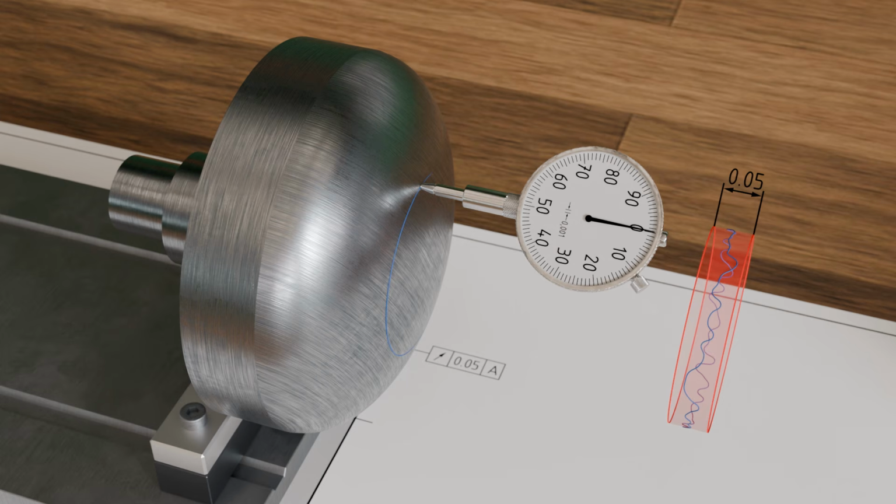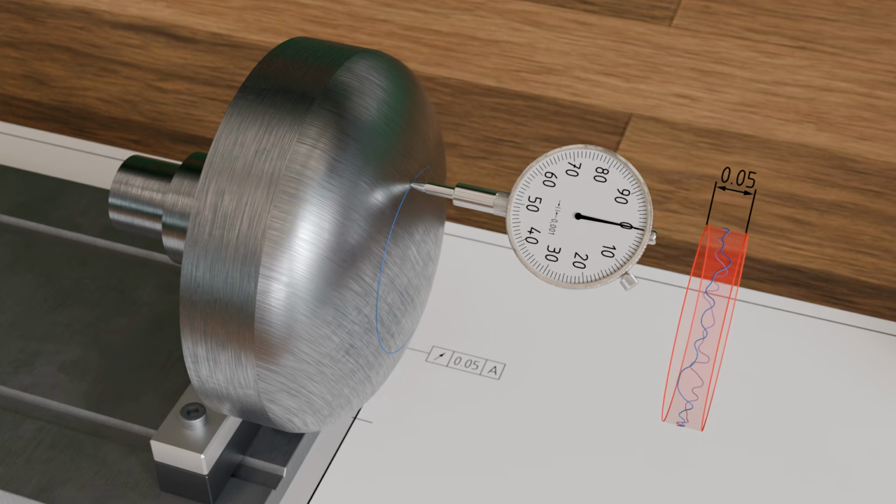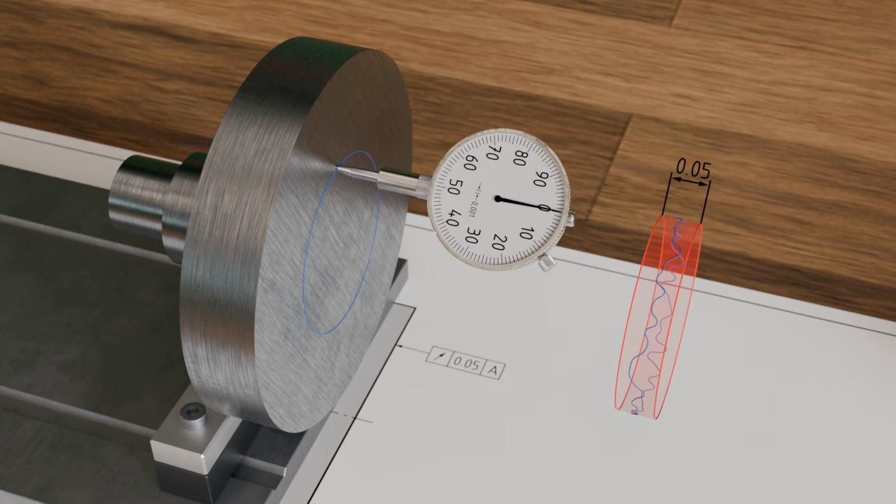However, this example also shows that if a surface is supposed to be as flat as possible, axial runout is not suitable. In this case, for example, axial runout would be met at all measured diameters and the part would be considered acceptable, even though such a convex shape is undesirable and the surface should be as flat as possible. In this case, it makes sense to inspect the entire planar surface in a single operation.